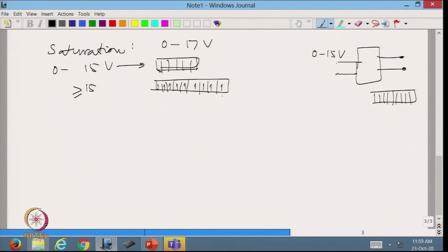So, you would not know by looking at this which is the data, which is what you will analyze later on after the data has been collected. You will find that here you have a bunch of readings which are all 15, 15, 15, 15 volts. Now, you should be very cautious in interpreting that type of information, because it could have been a genuinely 15 volt signal, but chances are it ended up having a problem of saturation, and this was missing out on something that was actually happening.